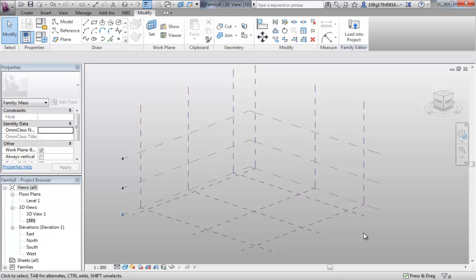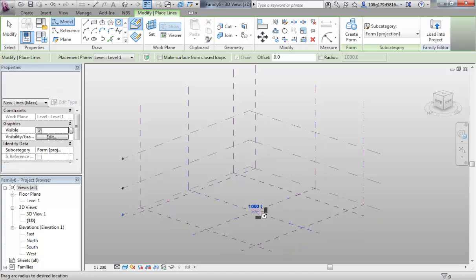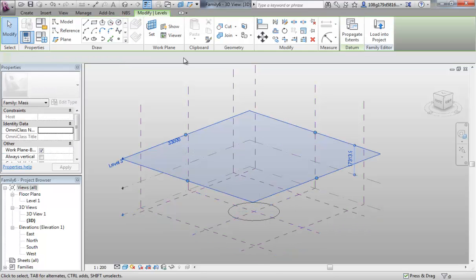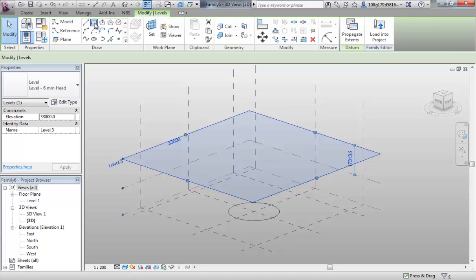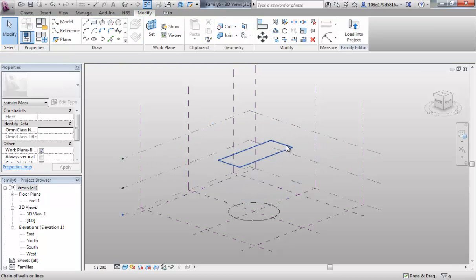First thing I'm going to demonstrate is a loft move. Now, a loft move is a way of combining multiple profiles, can be as many as you like, but minimum of 2, to create a form. If I was to do 2, select the floor, draw a circle, select the top work plane, maybe draw a rectangle.